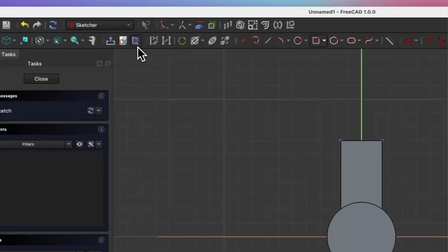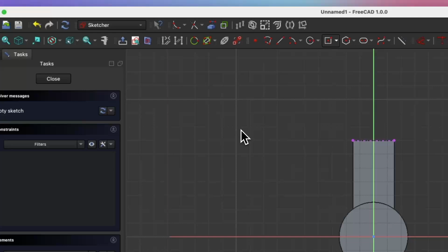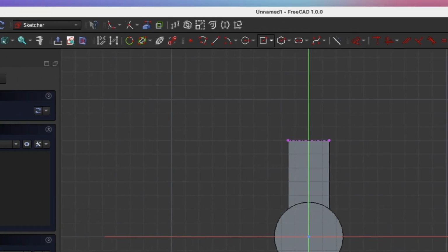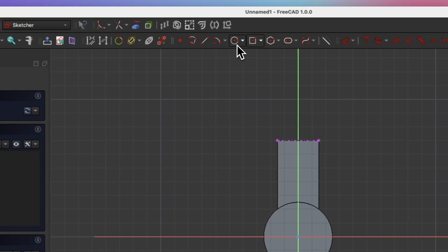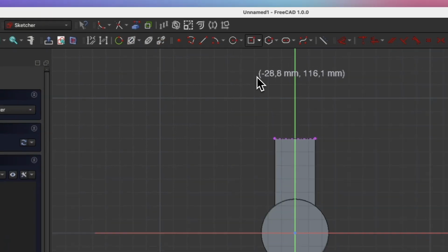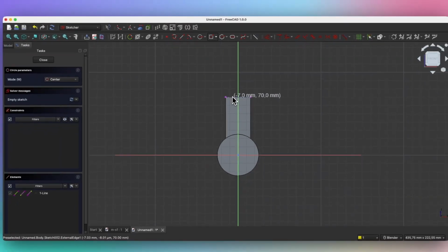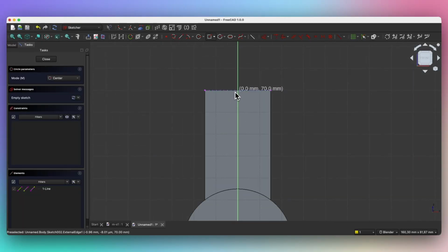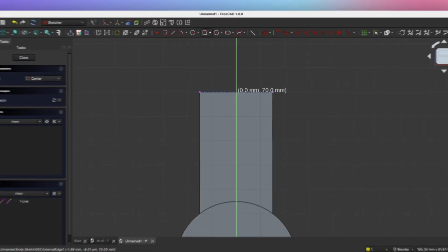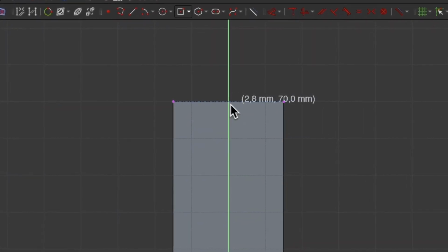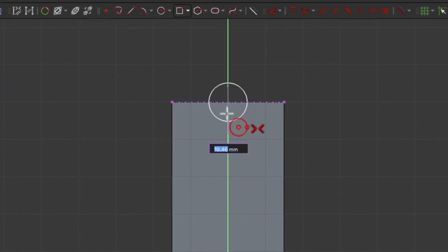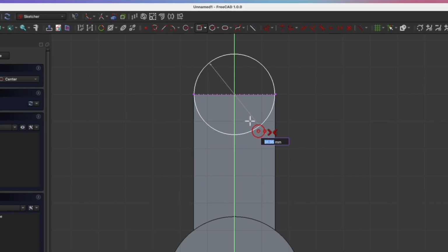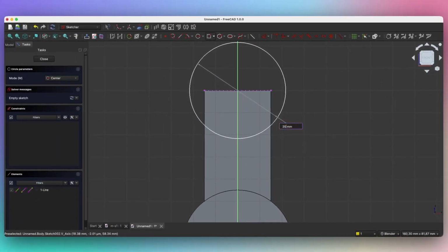And now click the View section button to switch to the Sketch Plane view. And select the Circle Drawing tool and draw a circle so that the center of the circle lies on this line. If you place the center of the circle close to the center of the line, then the symmetry constraint should automatically apply, which will position the center of the circle exactly at the midpoint of that line. Click here and as for the diameter, enter 35 millimeters and press enter.